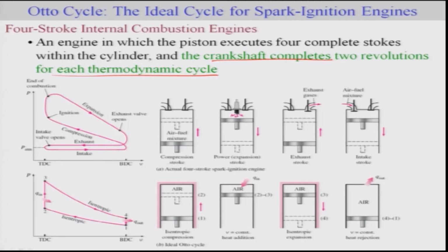So let me start with this particular first image. Here you have this inlet valve, and this is your exhaust valve, right? If you consider that this is the point you start your cycle, the initial point of your cycle, the inlet valve opens and hence you allow your air fuel mixture to come in. This is your inlet valve which opens, and this gas intake is considered here, and upon here the compression stroke takes you to the point where it's sufficiently compressed that you can start your ignition.